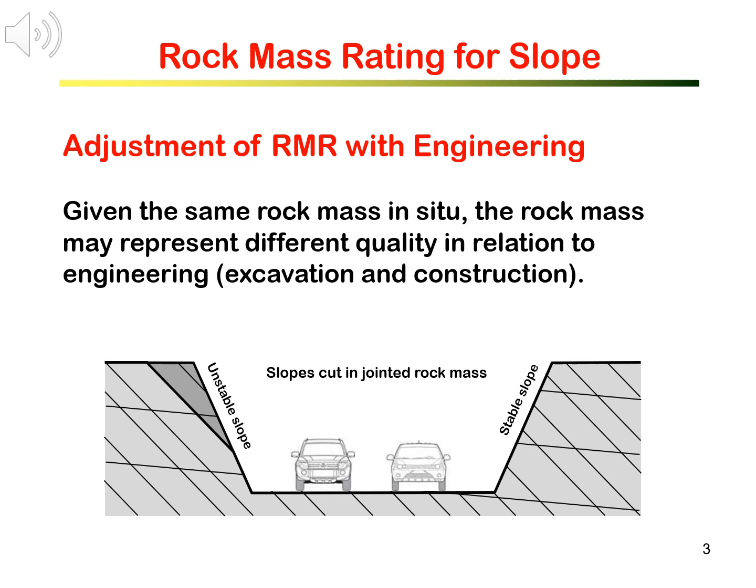No, you will see they are not equally stable. The left side slope is more likely to fail, as you can easily visualize that sliding down of the blocks. The right side slope seems quite safe. Well, the same rock mass, because it is cut in a different direction, the slopes have very different stability level.